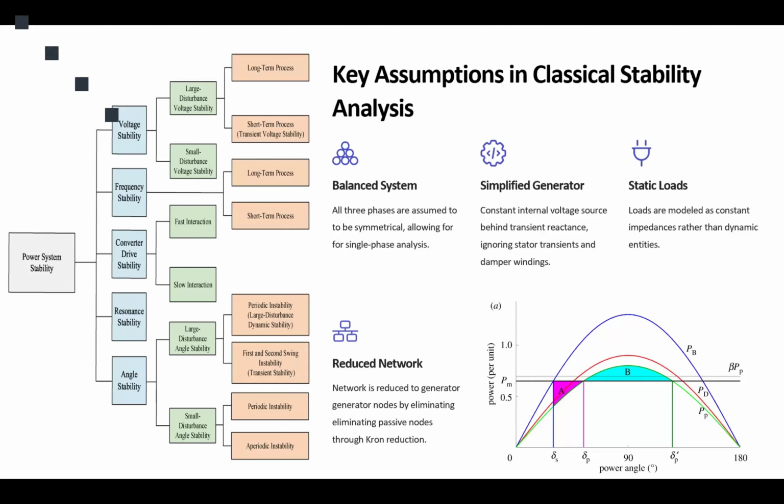Those are the electrical parts. There are tons of mechanical parts that kick in for that generator, which create a massive differential equation matrix for a generator to be analyzed in the real-time domain. To not get loaded with such massive computations, we are going to simplify our generators with a voltage and a reactance.